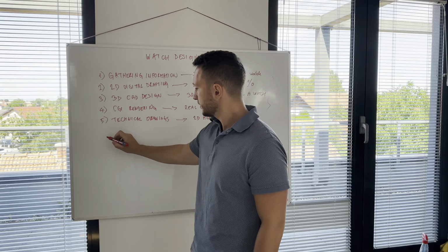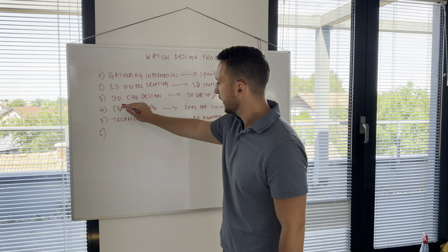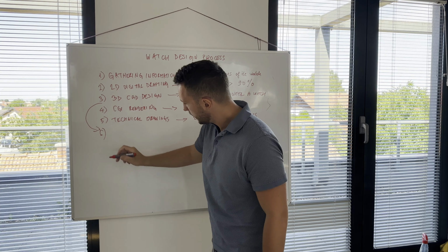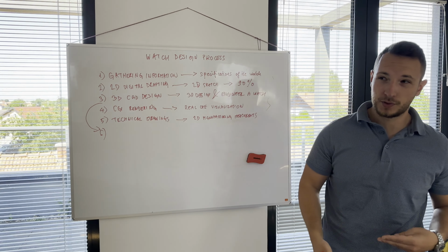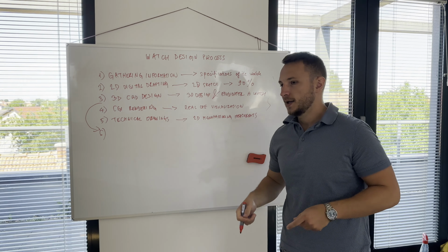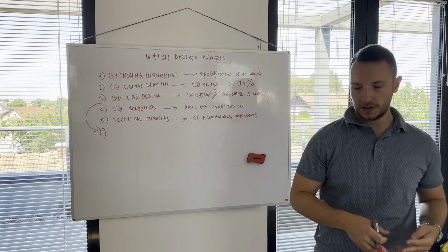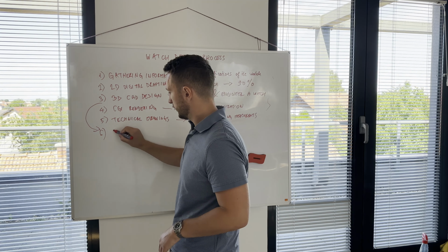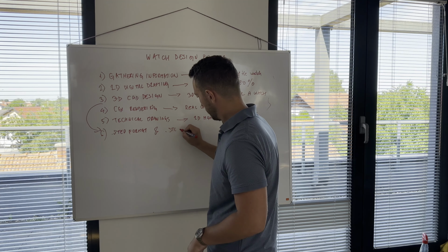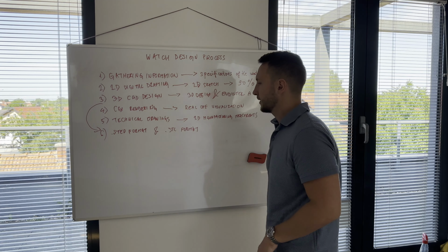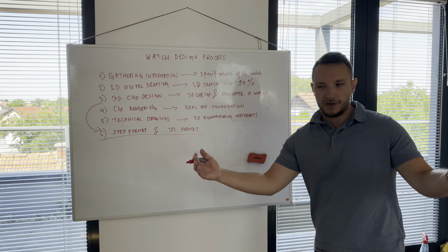And then step 6, that is the easiest possible step. You just export all of these CAD files. From step number 3, you export all of these files into multiple different formats. It very much depends on what software you're working with, and oftentimes the manufacturer won't be working with the same CAD software that you are. So I always export into STEP format and STL format. Those are the file exports that I always send out to the manufacturer.